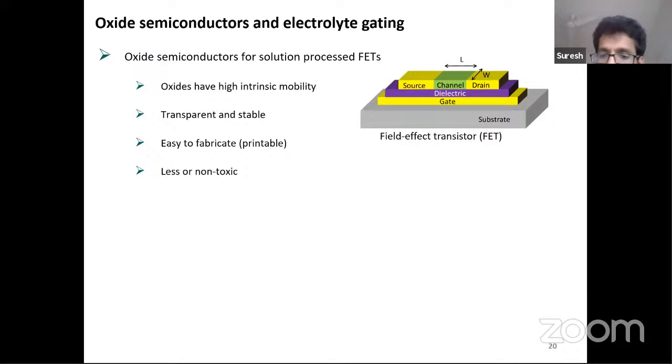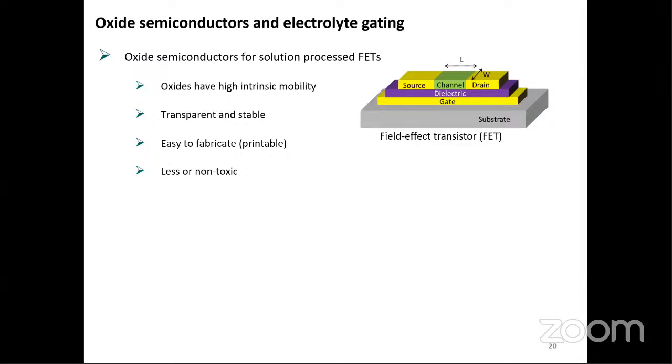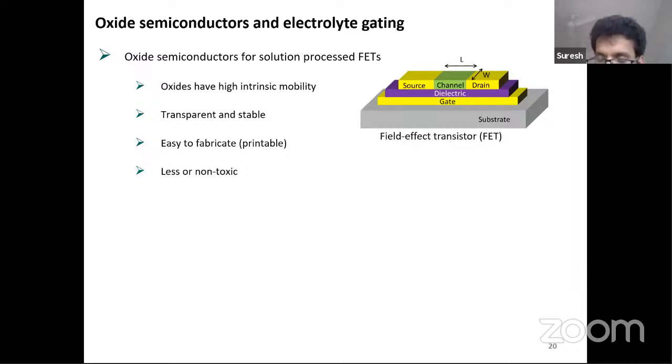Okay. Oxidation, let's say you take silicon, for example. Silicon is actually very reactive in air. So it reacts with oxygen. Loss of electrons, they are typing in the chat box. Okay, fine. Yeah, of course, oxidation is loss of electrons, true. And what happens is, for example, silicon is becoming silicon dioxide, right? Si plus O2 gives SiO2. So at room temperature, silicon actually oxidizes. So that's why you can't use silicon in case of printed electronics. So you have to use alternative materials.